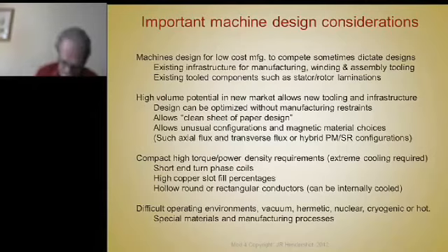But manufacturing people don't like that because it's slower, more tedious, and much more difficult to insert these shorter coils into the slots of the cores to get them over the teeth, to span the number of teeth they have to. So if it's automated machinery, you can have jams in machinery.